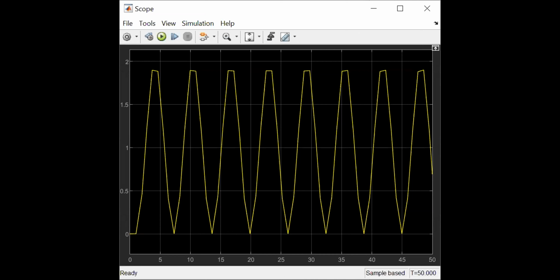And now say run. And when you run, your plot should be much, much smoother. So now you can see earlier I had that jagged plot because I used a variable step size, and depending upon the convergence criteria and other parameters, MATLAB chooses the appropriate time step, which may or may not be good from a visualization point of view, but I forced MATLAB to take a smaller time step. And now, as you can see, my results are much, much cleaner.